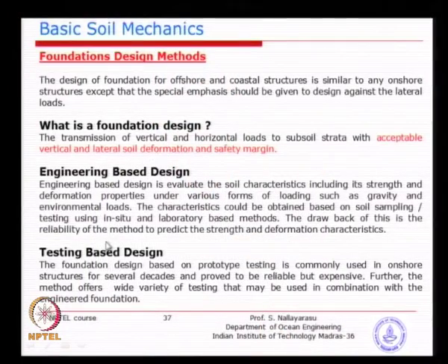It is massive, because you have to mobilize so much dead weight to simulate the superstructure loading, and it is time consuming and occupies large space. So, it is a lot of trouble. So, we have to minimize the number of tests, normally not more than 1 or 2 piles in a site, because of the cost and time.